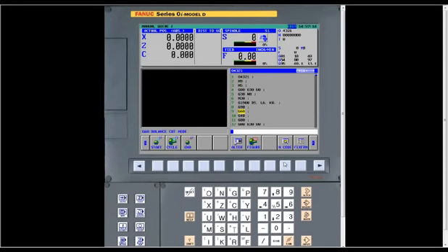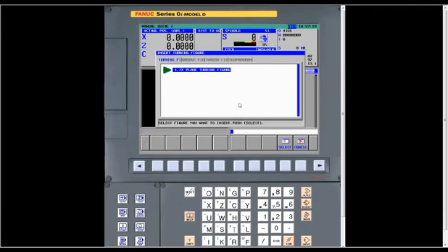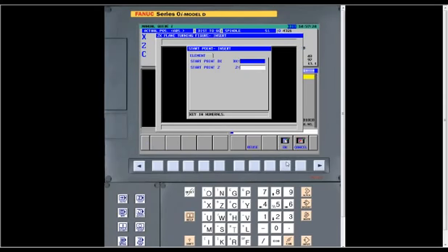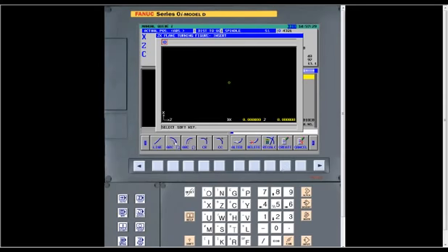Well, that's where when you go in to do a turning figure, Mark, you go in and you draw it. Once you select that, it takes you into a screen where you define the start point. I'm sort of showing it here. And then you have lines, arcs clockwise, arcs counterclockwise, corner radiuses.